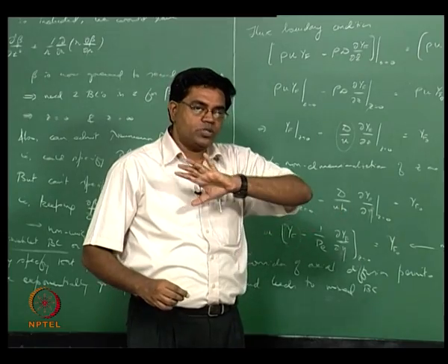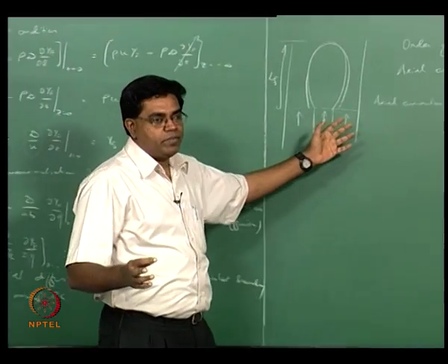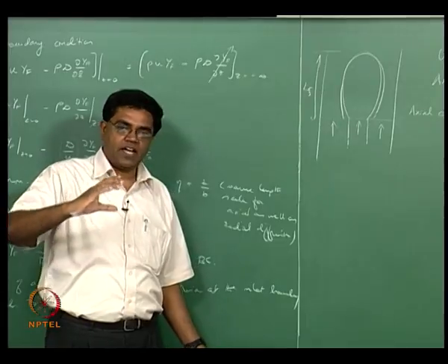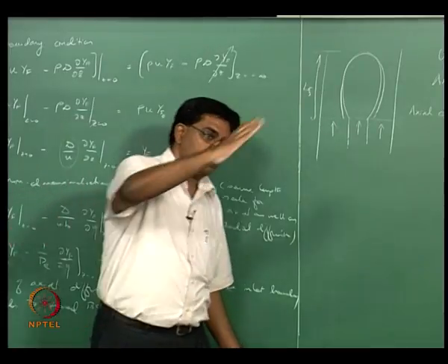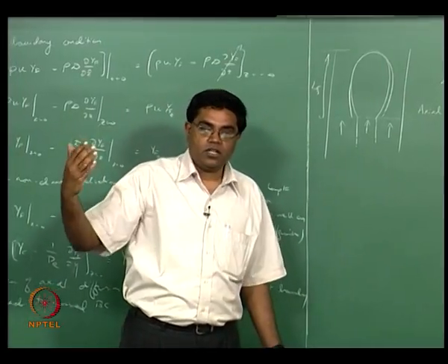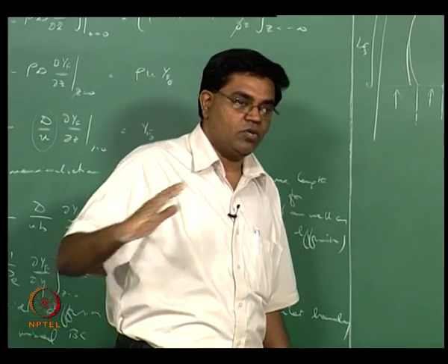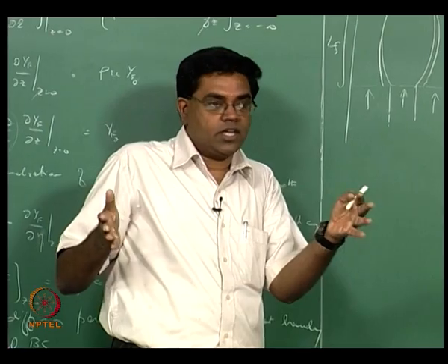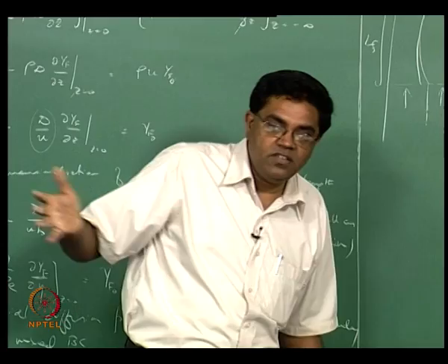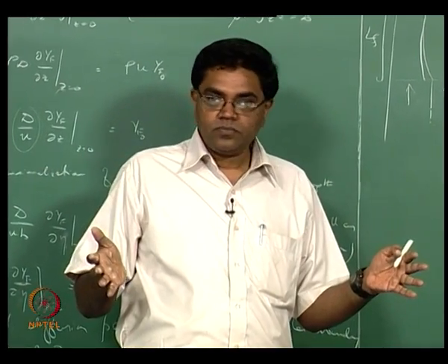So whenever you want to design the length of a furnace, particularly for diffusion flames, previously we saw what happens when you have ramjets and so on, or afterburners. The premix flame is held at the flame holder, and then it gets inclined as it tries to burn into the reactant flow, so that the normal component of the flow velocity balances the flame speed. Of course it could be turbulent flame speed, so you get the shape of the flame, and therefore you get the length of the combustor, all those things, right. Essentially the idea there is, what is the residence time of the reactants within this region, okay.